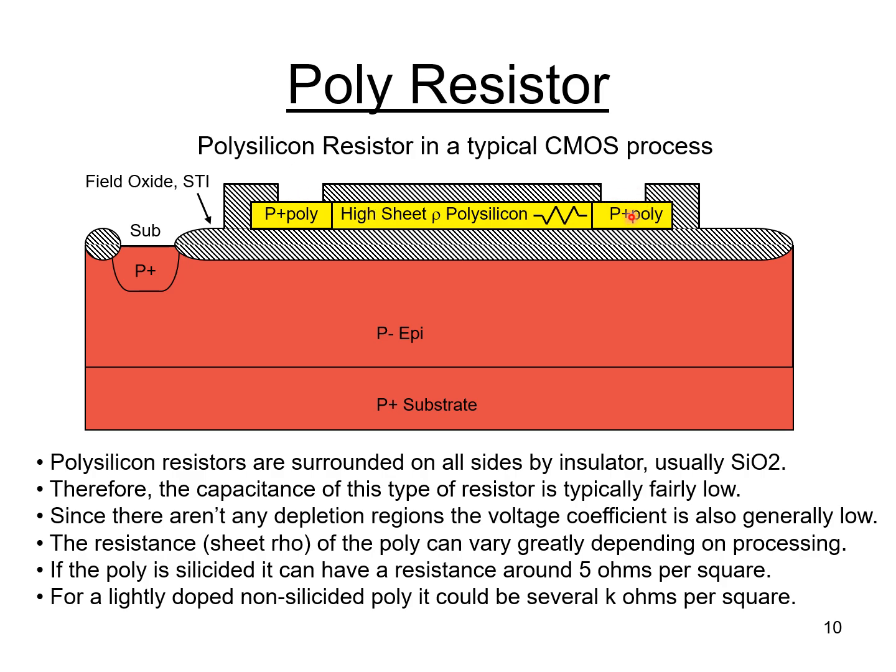The heads of the polysilicon resistor usually are silicided, meaning there's, and we talked about silicide before, a metallic silicon compound that is on the surface to give a good contact resistance. But then the body of the polysilicon resistor, you're going to want to block the silicide in that area so that you can get a fairly high sheet rho or sheet resistivity of poly in that area.